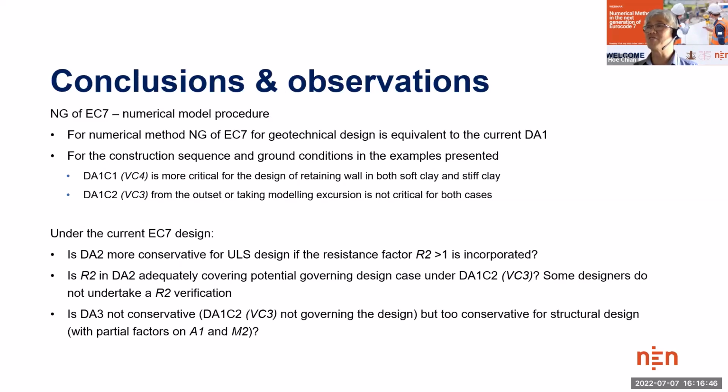Conclusions: for the next generation of Eurocode 7 for numerical modeling, the procedure is equivalent to the current design approach 1. Colin has said that, and I reiterate it. For the construction sequence and ground conditions that are presented, verification case 4 is more critical for both the soft clay and the stiff clay site.